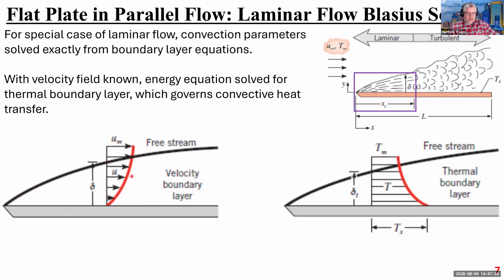So this is a velocity profile. The no slip condition applies at the base of the plate here, so the velocity has to be 0, and the velocity increases in the boundary layer as you get further and further away from the plate. When you reach this spot where the velocity is 99% of the free stream velocity, that's the edge of the boundary layer. That influence again grows as you travel down the plate, and delta grows with you.